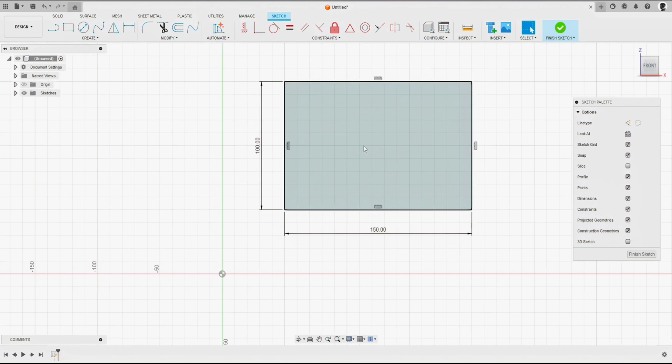Let's go ahead and apply some of these. Let's go for the equal distance chamfer first. And again, we can just select the corner point, or we can select the 2 lines. And I'll select the corner point for now. Let's go with a 20 mil chamfer. Press Enter. See if we've got 20 mil on the horizontal and 20 on the vertical.